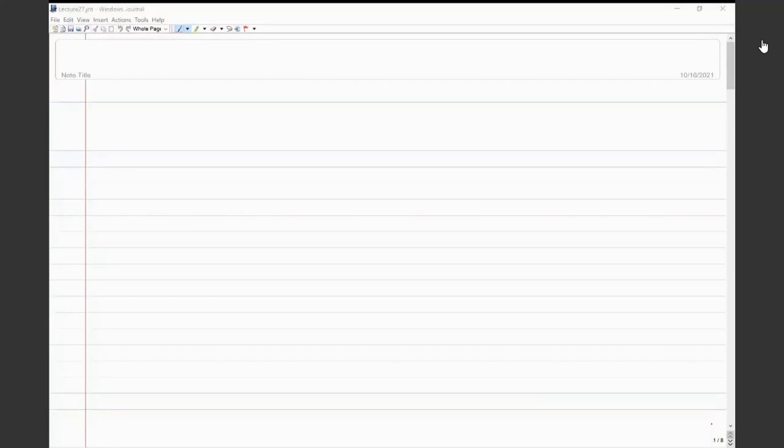Any other question, anybody? Okay, so let me start then. What is the procedure that we should follow to solve the damping problem? We should know the natural frequency first to find out alpha and beta. We should know the damping factor in two modes and the corresponding natural frequencies.